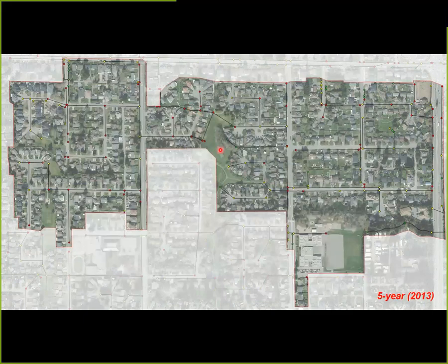But what this does not show you is the extent of the flooding. So we know there's some surcharge, but we can't differentiate between a puddle and a lake that might flood 20 houses, for example. That is the fundamental weakness of this traditional approach when you're trying to evaluate an event that's significantly larger than your design storm.